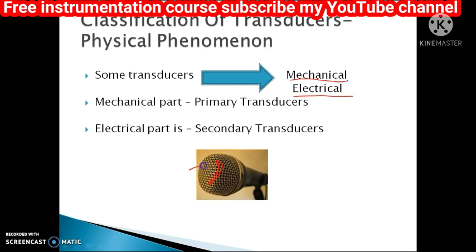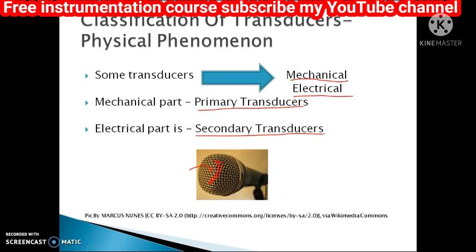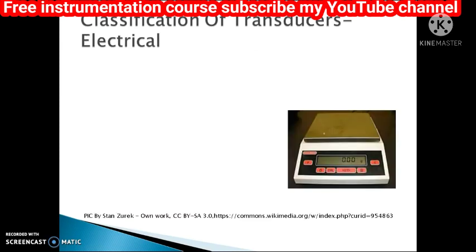So the sound waves which come will be converted by this diaphragm into displacement, and hence it will be called the primary transducer, and the displacement of the diaphragm, that is the movement of the diaphragm, would be converted into an electrical signal which would be called the secondary transducer.